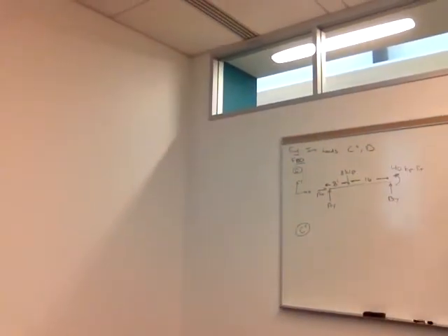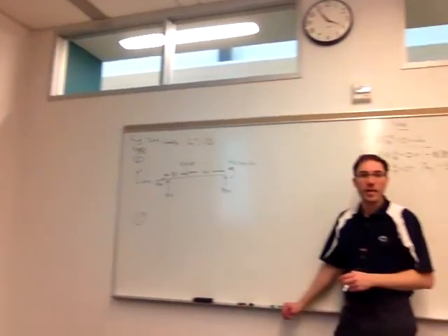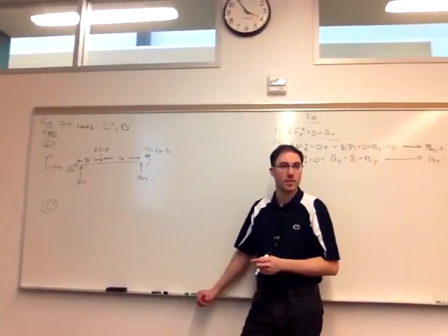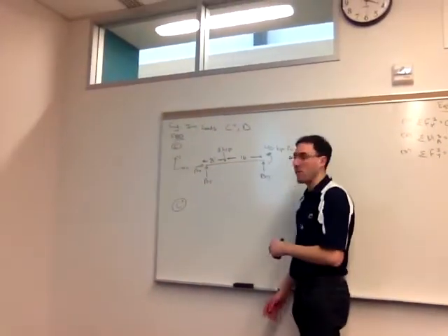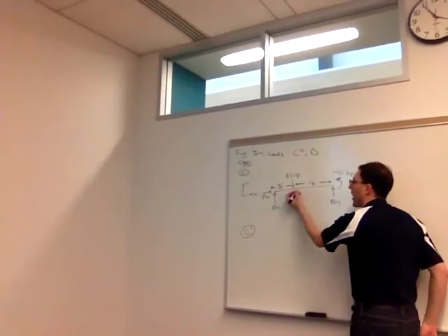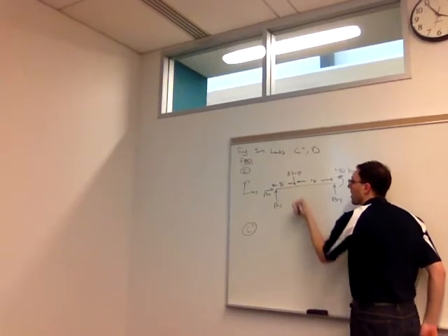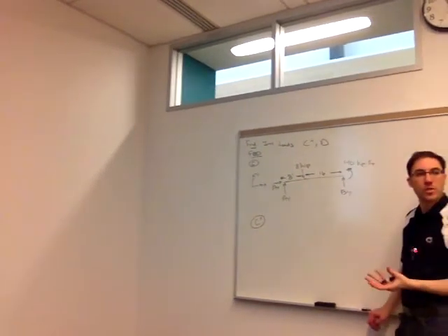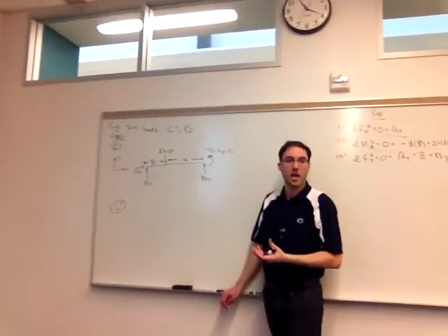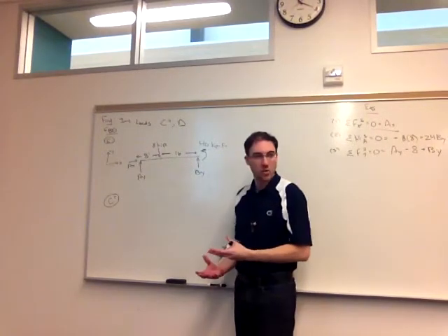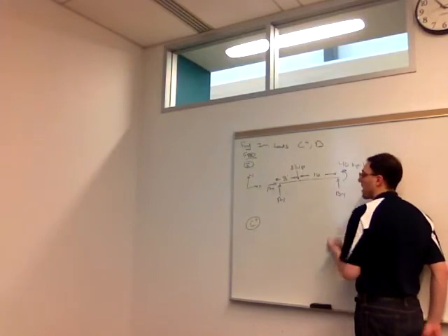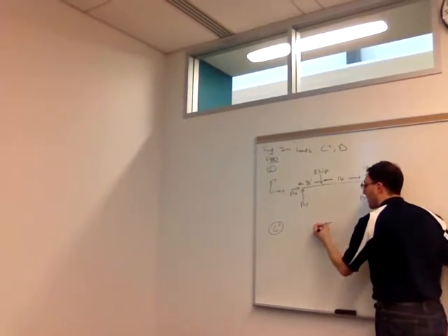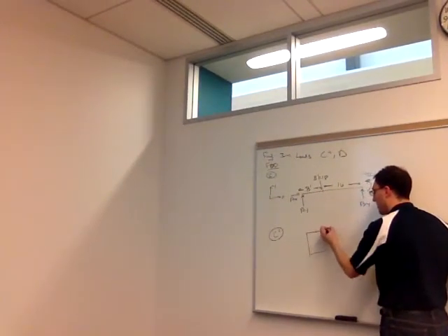So what I'm going to draw is a figure where I'm cutting it just to the right of point C, and then I'm able to keep everything to the left or everything to the right. So I'll use this as a demonstration. I'm looking right here at making a cut. As with trusses, I usually want to take the less complicated side. The answer will be the same, but I can keep everything to the left of that cut or to the right of the cut. In this case, I'm going to keep everything to the left of the cut.